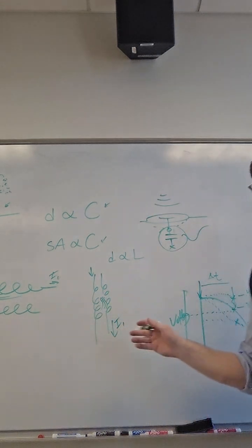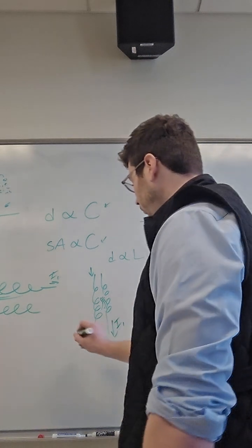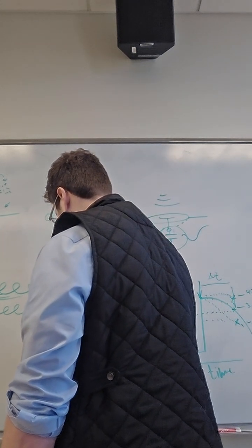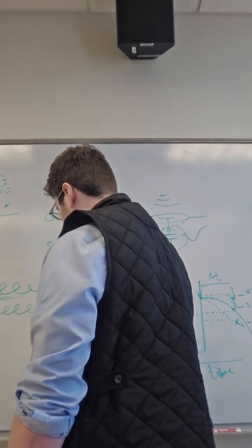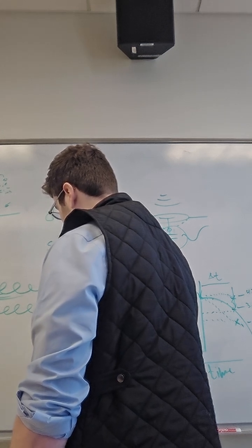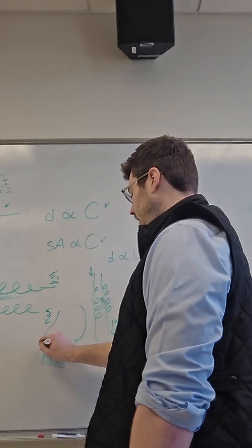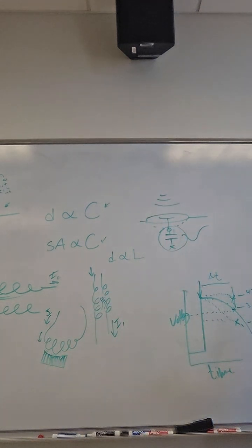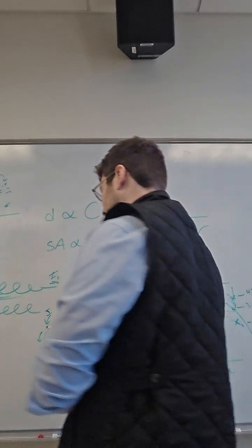For example, we could be measuring the air in between two coils and how that changes. The presence or absence of different gases or radiation or metal. All right, for example, one way that metal detection is done is that we have a coil that's energized and we're just running current through all the time. When we're in the presence of a ferrous metal, metal has a higher magnetic permeability than air, which means that the inductance of our coil suddenly goes up. It becomes a better inductor when there's iron nearby. It can store magnetic energy more easily. Okay, it's like a booster for magnetic storage.